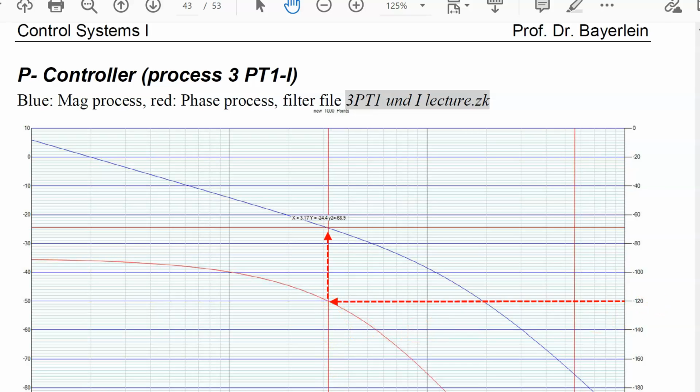The cross point gives here the resulting value 3 and a little bit more, so 3.2 or so. We measure here 3.17, I round to 3.2 per second. So that we have advanced, if the Bode plot is ready, within some seconds we have the design completed.